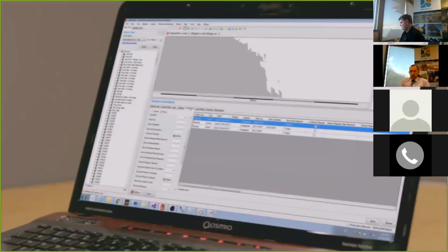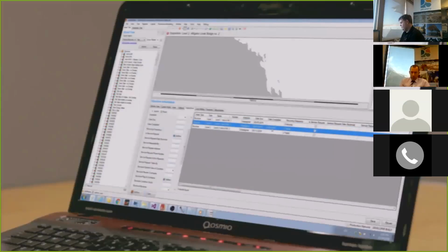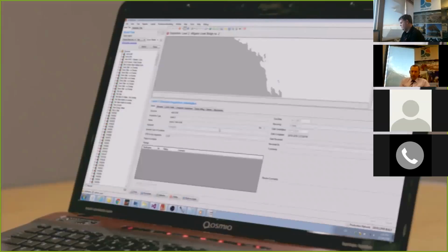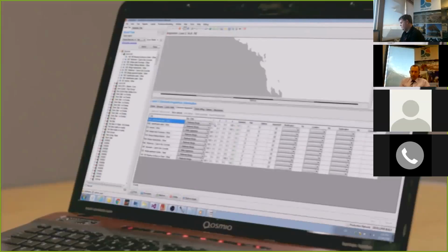That's where we derive the condition of the individual components. We need a completed condition inspection. As you can see, we have one here. We need to make sure the units are fully assessed. We're using a condition range of 1 to 4 according to the VicRoad standard. We'll also want to make sure we specify an exposure class because that allows AssetAsyst to determine a more accurate estimated life for the components.